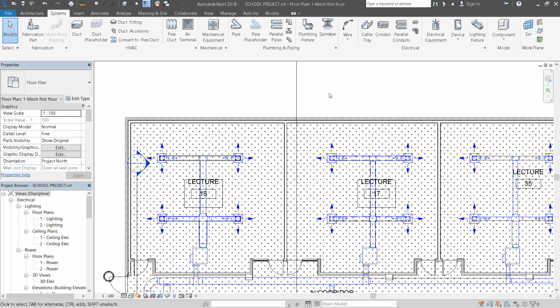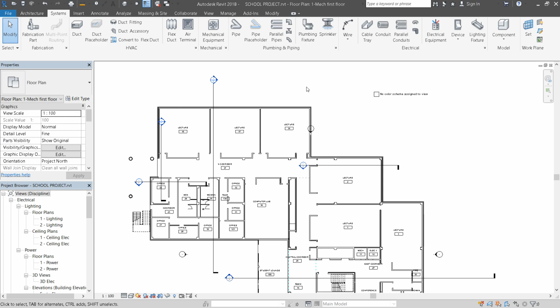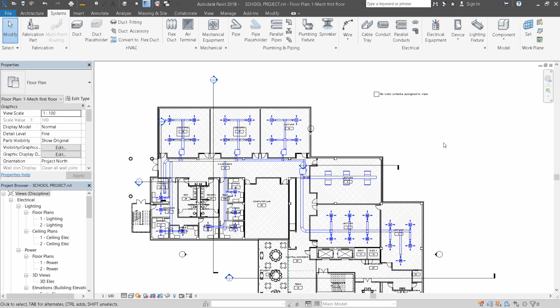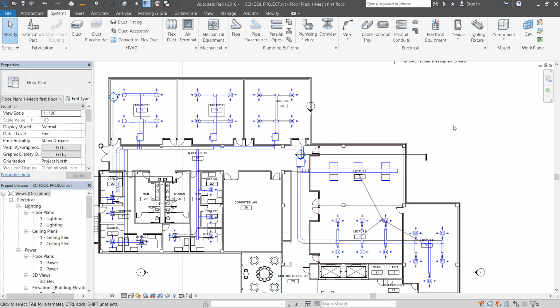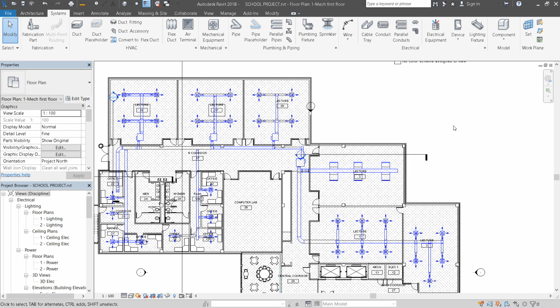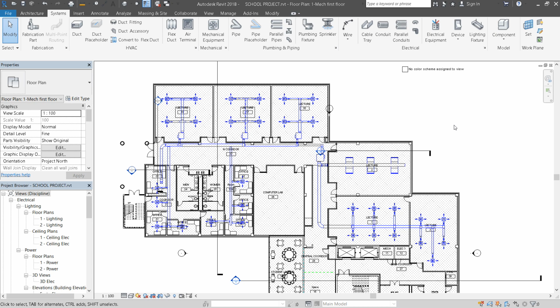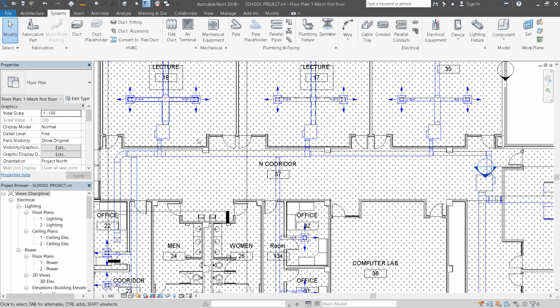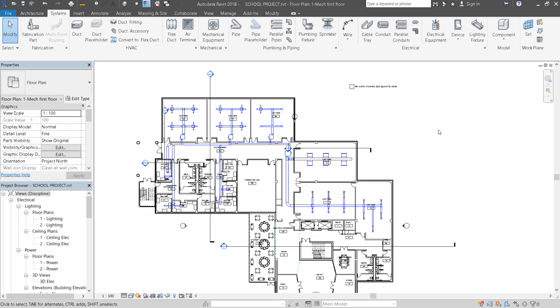So likewise, you can place your insulation over here based on the system. So this is how to create one zone system, as well as check that your system is completely okay. The flow is perfectly provided to each system, and you can resize the system based on your selection, at equal friction or equal velocity, static pressure or whatever. Based on that you can resize your duct system. Okay.